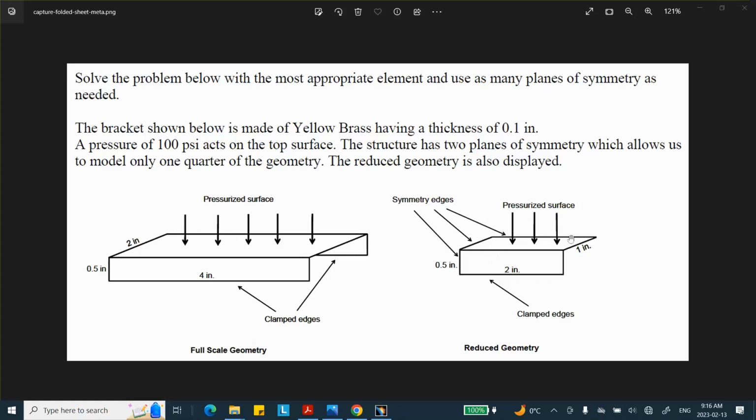Right away, a single surface composed of 2 pieces is created. I don't have to join it. It's not necessary because of the way it's constructed. They are already seeing each other. And then when it comes to meshing, I will put a thickness of 0.1 as 2D property on that surface that I create and use the local 2D property in order to change one of the thicknesses.